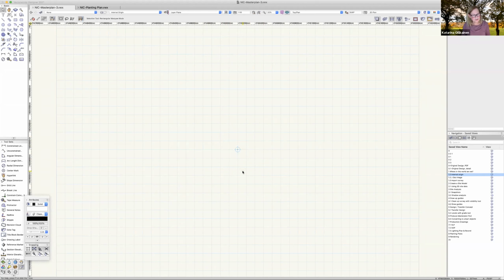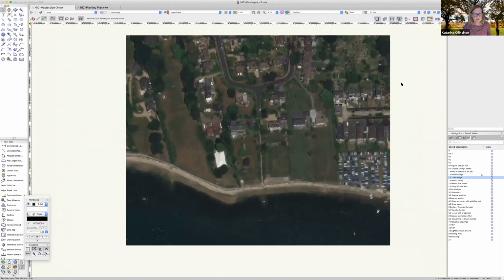And then I can hear, of course, you say, well, one of my projects is in Aberdeen, another one is in London. How can I stay within the 5-kilometer range? Well, the good news is that you can tell Vectorworks what coordinates of the national grid are supposed to coincide with this dot, with this internal origin. And that's what I've done here. If we go in and look at this image, I have pulled in this geo image from the site where we're going to work right here. And I set it up so that the coordinates line up with the internal origin for where we are.